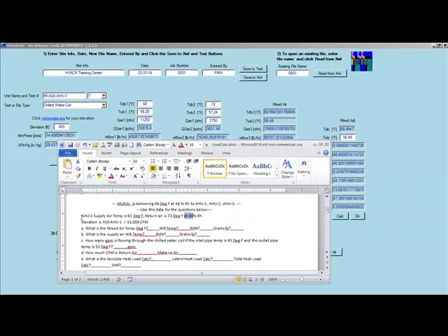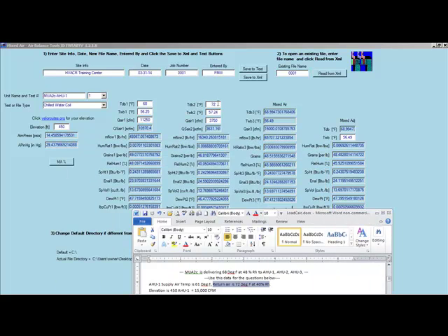Okay, so air handler 1, the supply air temperature is 61 degrees, but for our mixed air, our return air is 72 at 40%. And as you can see, we have 72 degrees dry bulb, and we're about 40.05%.